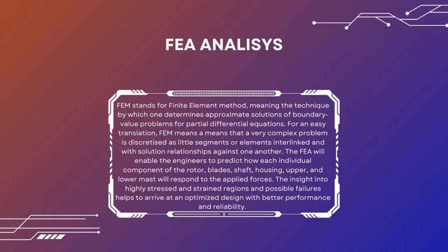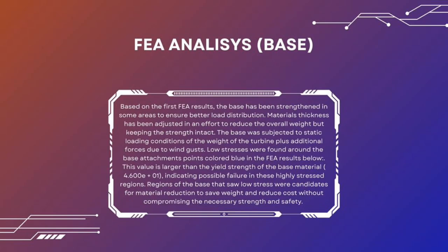The FEA will enable the engineers to predict how each individual component of the rotor, blades, shaft, housing, upper and lower mass will respond to the applied forces. The insight into highly stressed and strained regions and possible failures helps to arrive at an optimized design with better performance and reliability.